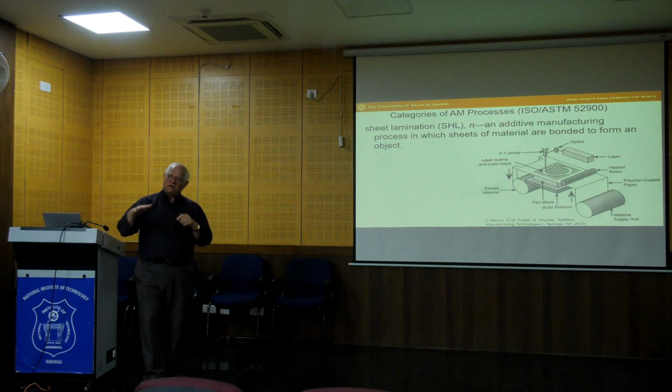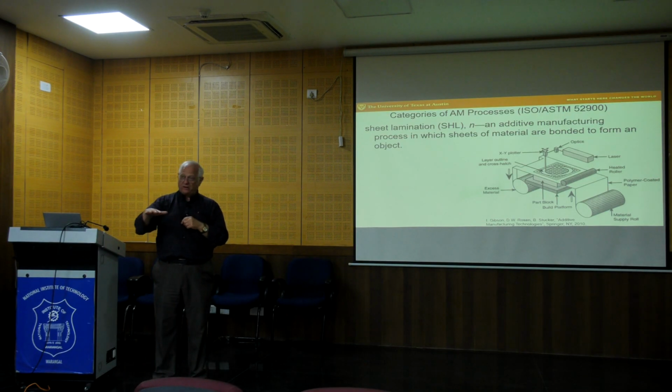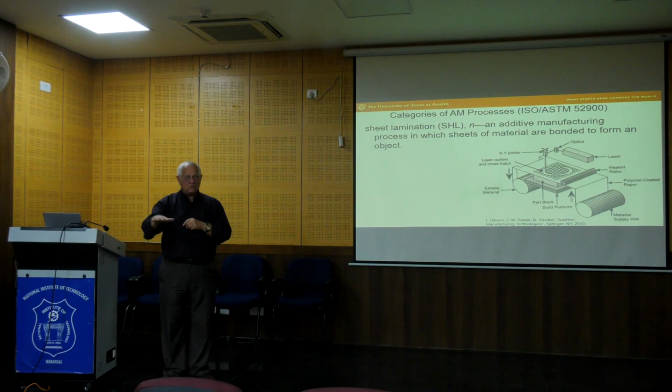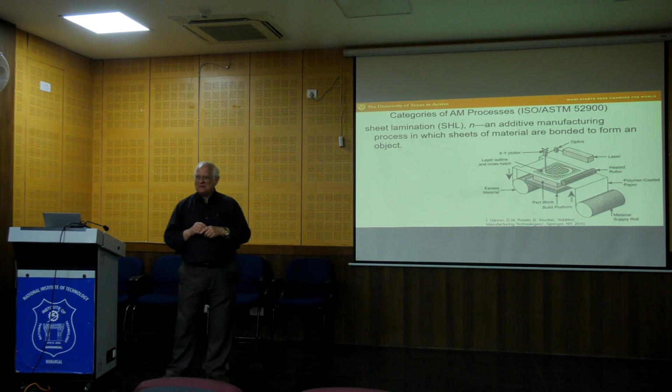That does this. And what they do is they take a thin piece of metal foil and lay it down over a build surface, and then come in with an ultrasonic sonotrode, which is basically a vibrating cylinder. They roll it across the foil, and it actually mechanically welds it, solid state welds it, to the previous layer. And so they can use this to build layers without geometry, but then every few layers, they come in with a milling head and machine out what the surface looks like.